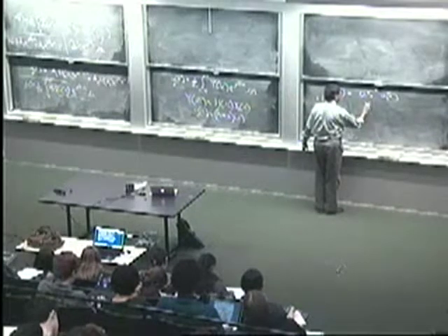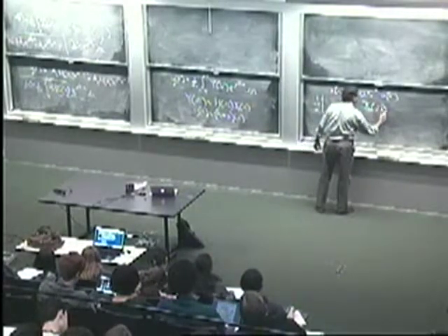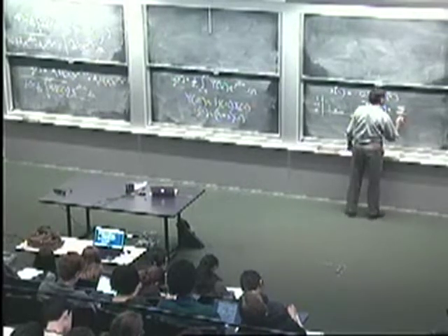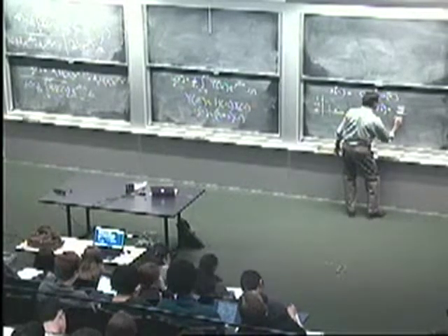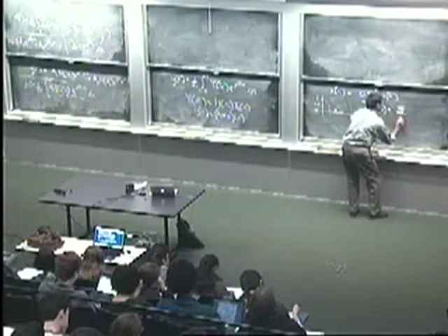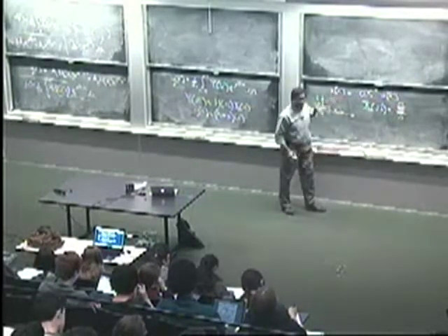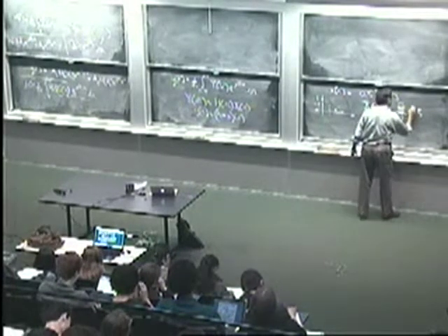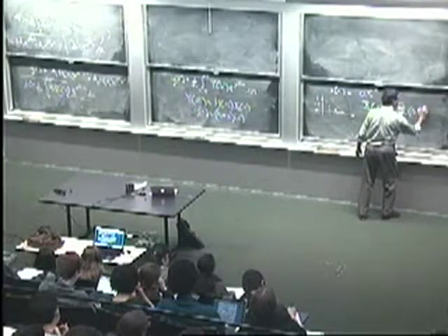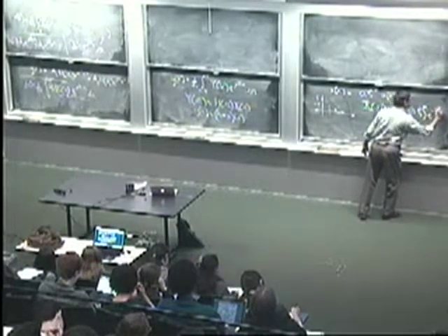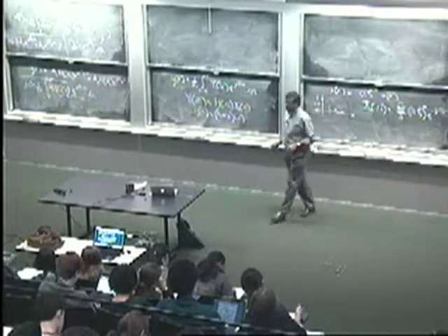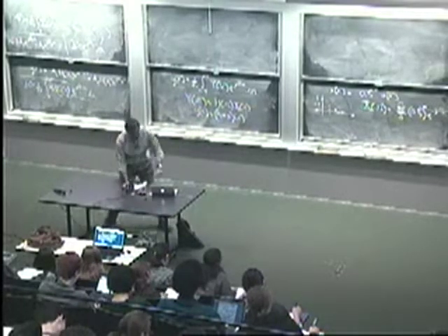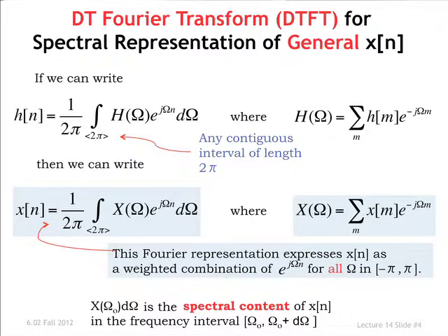All right? And so what's the DTFT? Well, you're going to sum from m equals minus infinity to infinity, but actually this only exists for non-negative time. So you're going to get 0.5 to the m, or let's keep it at m, times e to the minus j omega m. Right? That's just the definition. Okay? I've just used the definition.